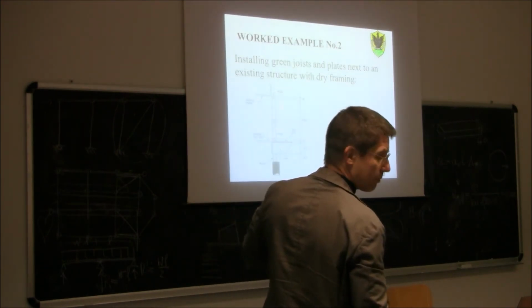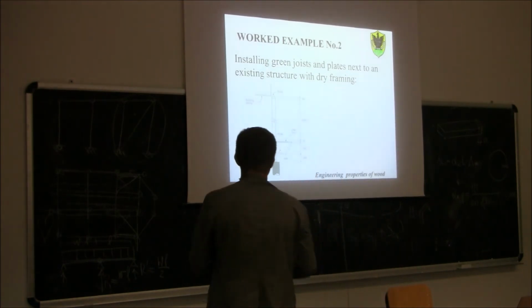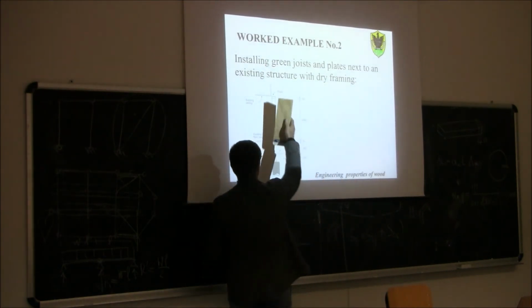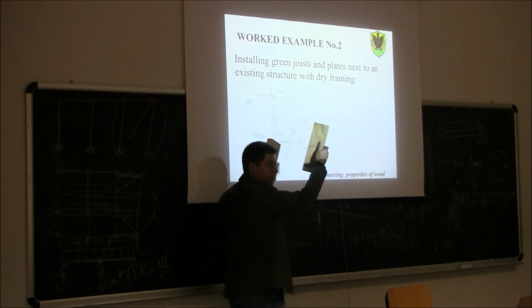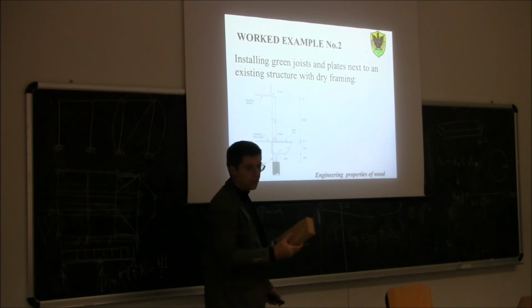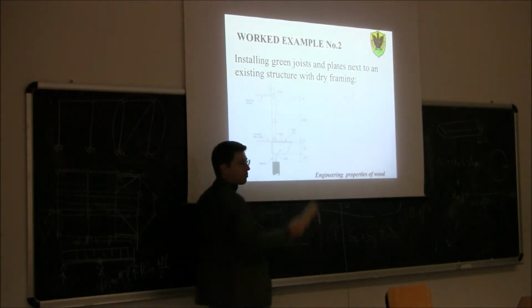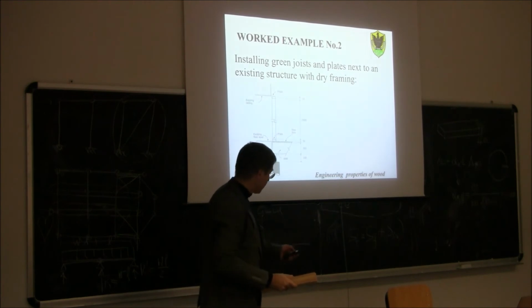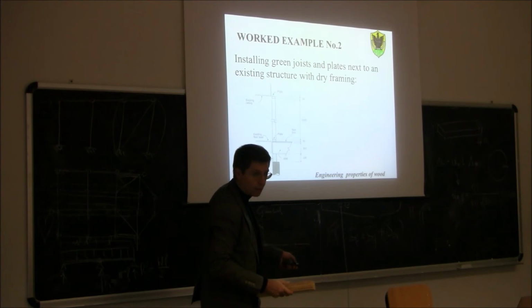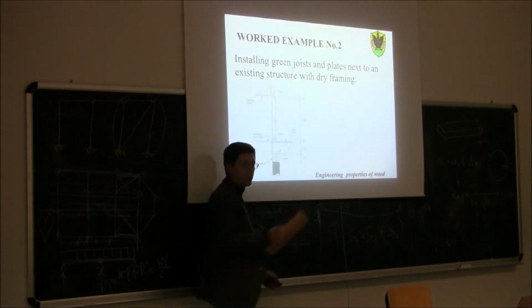The biggest, this one. Are you sure? To think about it, I calculate the shrinkage of this member here, which is the longest. But which value of moisture dilation coefficient do I need to use if the shrinkage is parallel to the grain? I have to use this value here, 0.00005, which counts hardly anything. So is it sure that this would be the most important contribution?